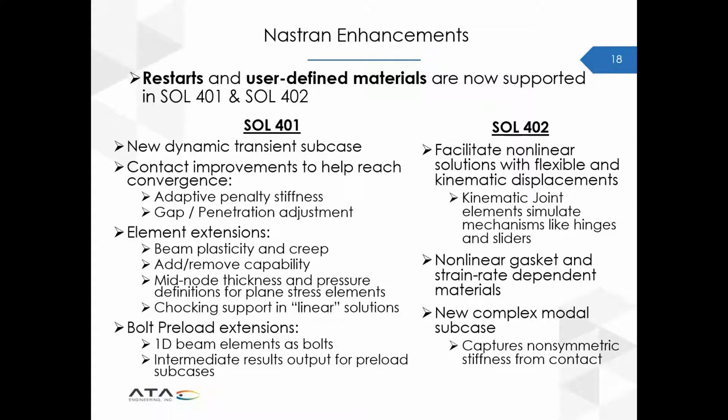So this is a universal connection that I was talking about earlier. This makes it easier to model things like hinges or sliders or spherical connections. In addition to that, solution 402 has some new nonlinear gasket and strain rate dependent materials that are supported. And then there's also a new complex modal subcase that captures non-symmetric stiffness from contact.